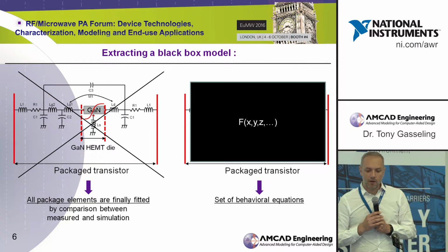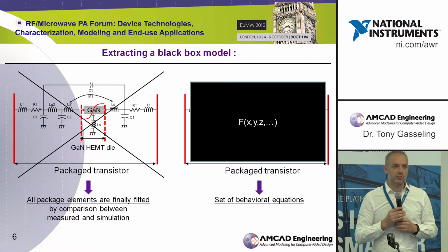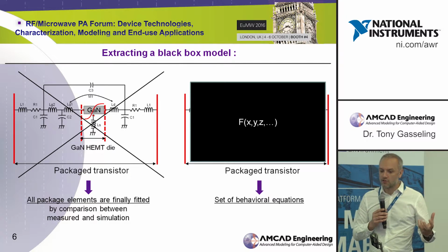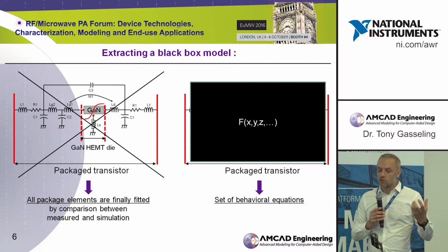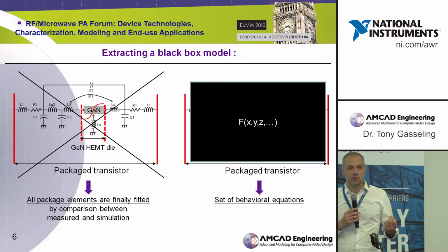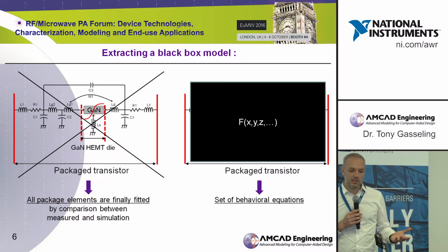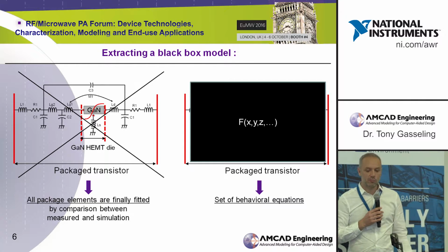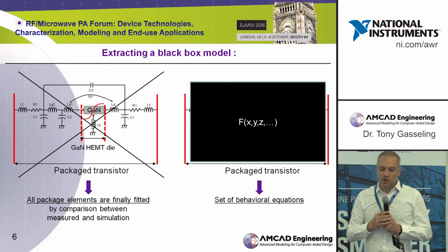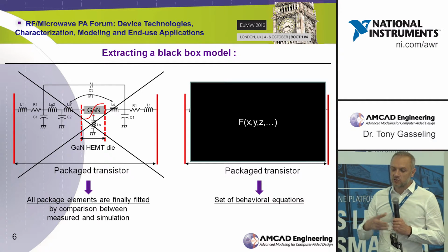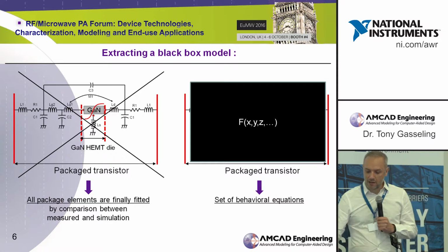This is why behavioral models make sense, because from the perspective of the power amplifier designer, you just need a tool. You don't care about how the current source behaves and so on. You just know the biasing conditions you want to use according to the transistor you will choose. And from this, you will define the operating conditions, that is to say the frequency of interest regarding load pull measurements and so on. And you want to use all this knowledge to extract a mathematical model, a black box model.